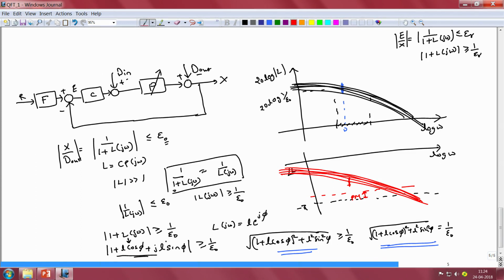Hence, it is not possible for us to extract just a single curve from the magnitude characteristic and the corresponding phase characteristic of that loop gain and just design our feedback control system for that curve alone and hope that our design is going to be valid for all other curves. Even if it is likely to work, it might result in an overly conservative design, because the worst case magnitude characteristic need not necessarily correspond to the worst case phase characteristic.